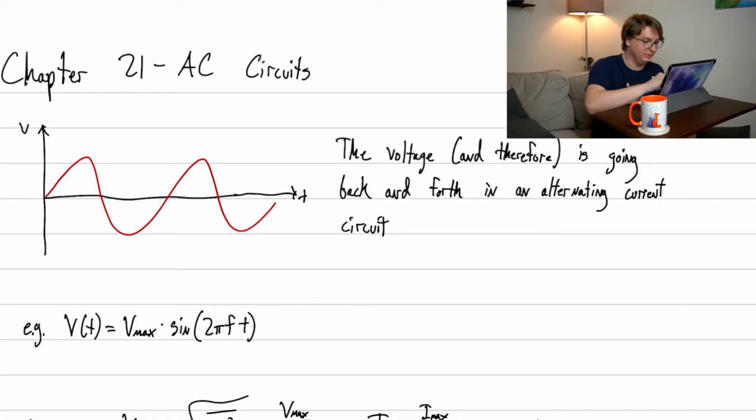So what do we mean by alternating current? We mean that the voltage looking at any given point in a circuit is going to be changing. It's not going to be the same value. It's not going to be static. So at some point there might be no voltage, looking at the difference between two points, or maybe just consider the voltage of a resistor, but then there's going to be some maximum value, and then it's going to switch direction. So that's essentially all we mean. And we can often write this as being some maximum value times some sinusoid, some sine or cosine. Sines and cosines are the same things except shifted by a phase. So often we may just write it as a sine. So we put in a given time. We have some frequency that's being created by a frequency generator. We put in that. So we'll be working a little bit with this equation.